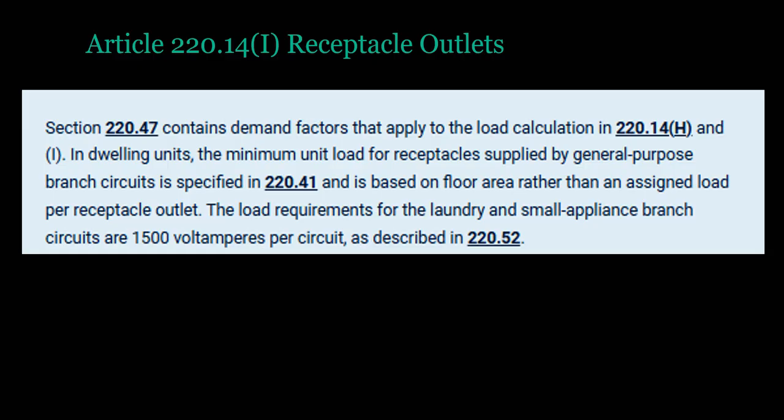Fun fact, which I've learned in my brand new book, 2026 Changes: that multiplier of 3 volt-amperes per square foot, in the 2026, they have changed it to 2 volt-amperes. The reason being the advancement of LED lighting and the reduction in the loads. Something else being pushed in the NEC now is copper-clad aluminum.